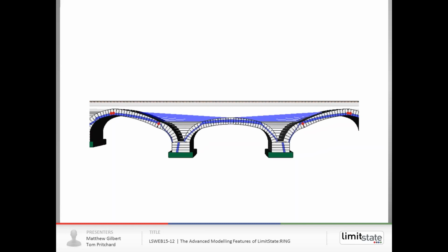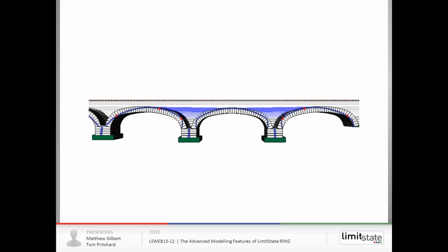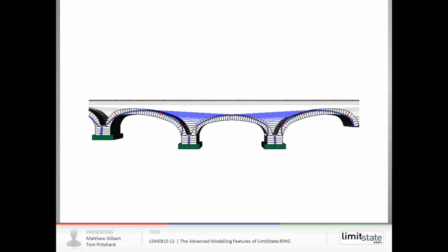What I then did was develop a new model with a reduced amount of backing above each pier. You can see that led to a change in the predicted hinge positions, to positions quite different from those we see in the bridge in the field. So in other words, the previous model was almost certainly right as far as the amount of backing.